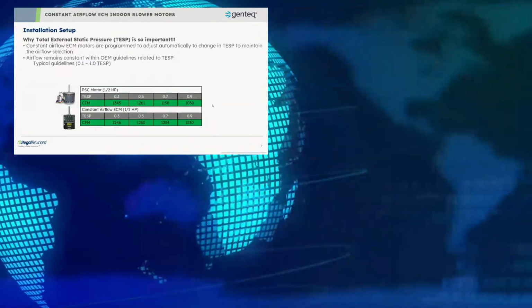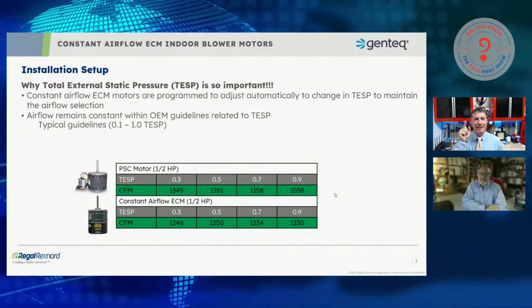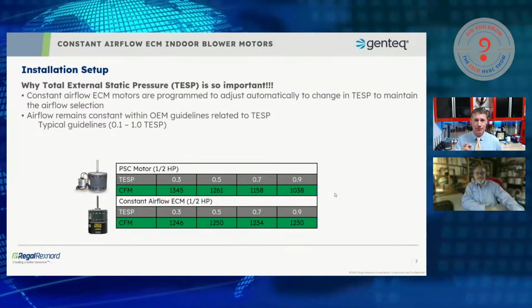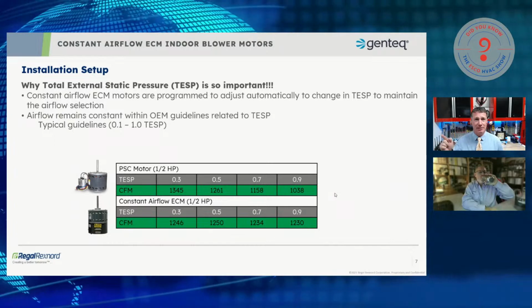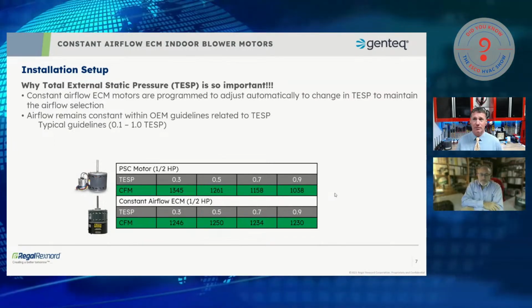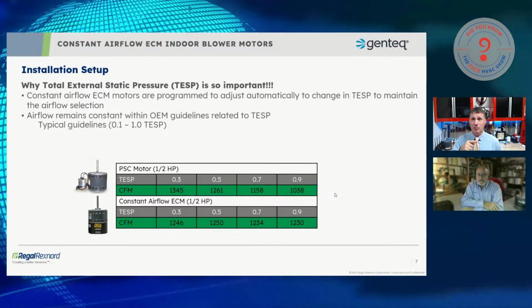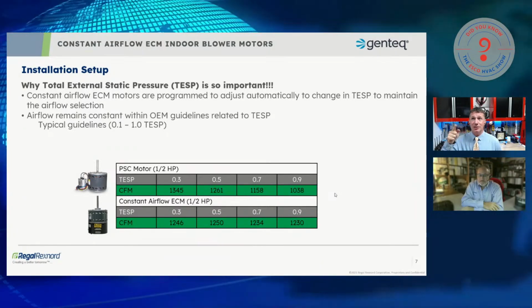Thank you. I used to threaten my dealers with this right here. If my static pressure on an installation is outside of my manufacturer's recommendations, I could potentially void a warranty on a product because it was improperly installed. The manufacturer says it is only capable of this.